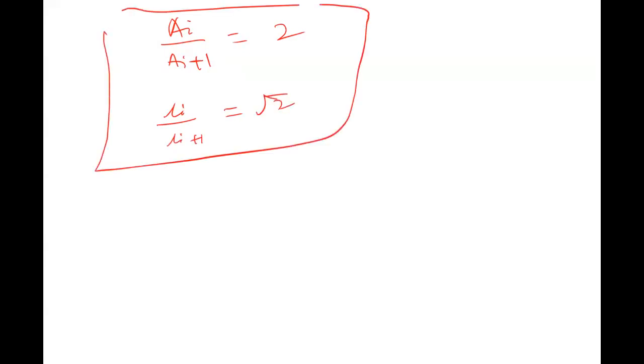It is assumed that in the Taylor standard screen the geometry of the opening will be square, so obviously the ratio of actual dimension to that of the next screen is root 2. The mesh is the number of openings or holes per linear inch. Is it clear? Yes or no?